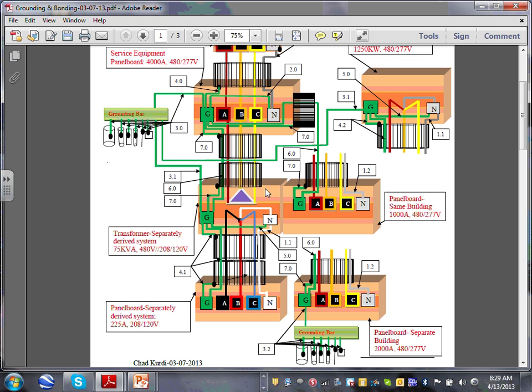That's very common. So taking a feeder from here to a typically delta-wye transformer, my separately derived transformer right in here, and from the transformer we took a feeder to feed a separately derived panel, aka your receptacle panel, right? So that branch here, that feeder through the transformer, has a special grounding and bonding requirement. Don't you guys agree with that? So that's why I picked that particular scenario to do grounding and bonding for it.